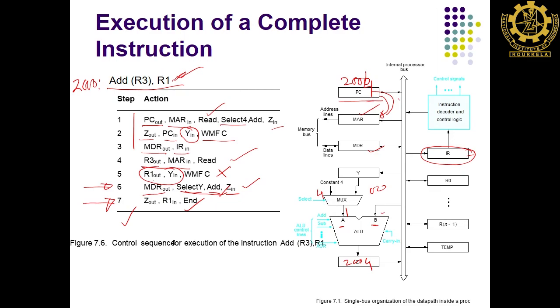Jump instruction means program counter value will change, program counter sequence will change. So, after fetch remains the same, after decoding it will realize that it is a jump instruction. So, program counter value immediately needs to be changed. So, how will it realize?